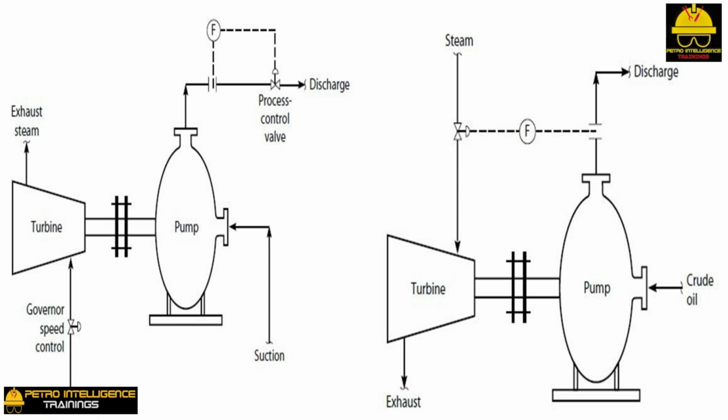The turbine speed is then always at its optimum. The delta P across the process control valve is always zero, because there is no process control valve. This design is a direct descendant of the original method of controlling the steam flow to pumps. The steam inlet valve was opened by the operator, so that the desired discharge flow was produced. Why, then, do we need process control valves on the discharge of variable speed-driven pumps? Why, indeed.